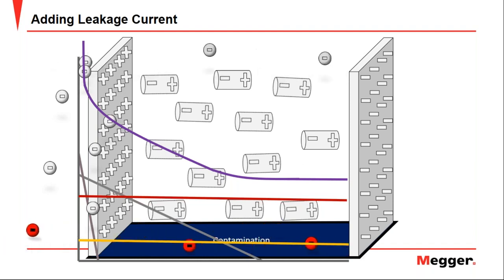That is why the IEEE 43 standard establishes that when the insulation resistance test is carried out, the measurement must be made after 60 seconds of reaching the test voltage, to allow the discharge of the currents that we are not interested in, to avoid that they affect the measurement.